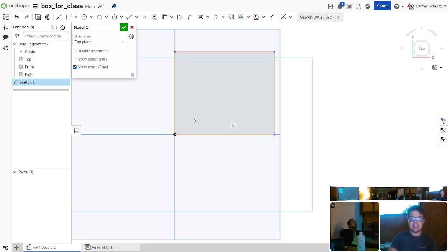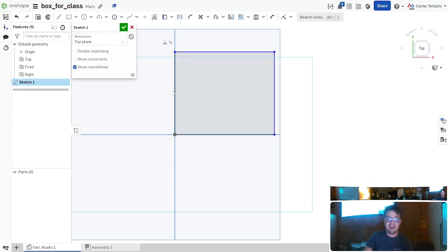And you can see, as I move my mouse around to different locations, different of these little constraint symbols pop up and appear temporarily. Those are automatic constraints that it put into the geometry for me, like the fact that this line is perpendicular to this line is controlled by this little constraint. When you get good at OnShape and know what's going on, you don't have to think about these constraints too much, and they're pretty automatic. As you're starting out with OnShape, I think it's really useful to check this Show Constraints box that then just makes all of the constraints that exist automatically appear.